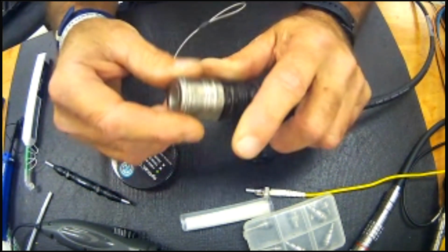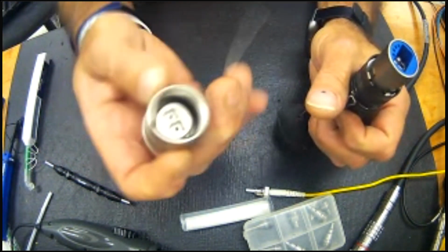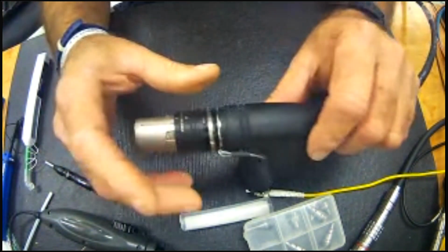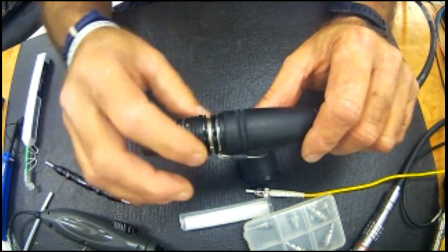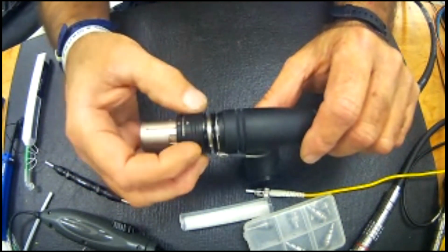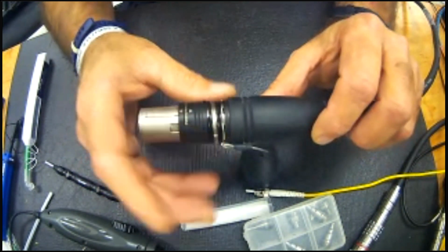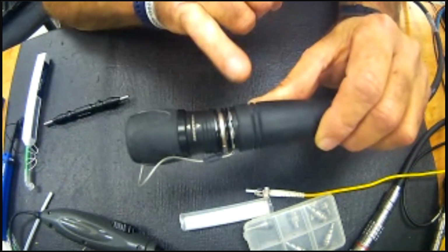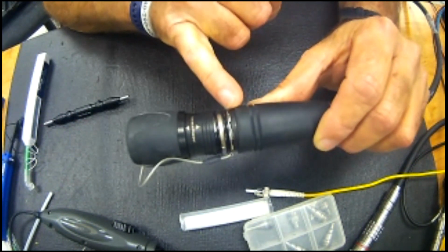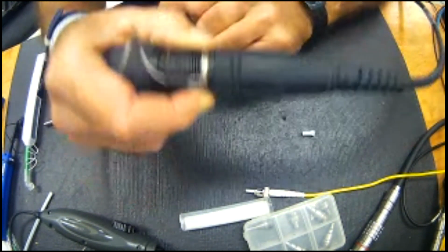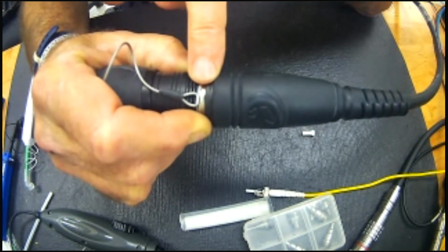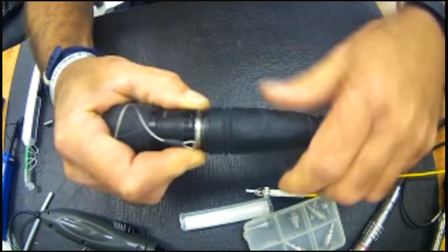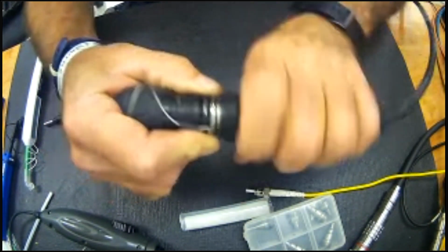That's one approach. Another approach, if you don't own this, because this is proprietary to this connector, is learn to take this connector apart. I've had repairs come to me with channel lock marks and vice grip marks because somebody didn't know that in order to take this connector apart, you have to retract this spring to move this wavy washer, the slotted washer, away from the back nut. Why? Because the back nut has raised teeth on it. So those teeth will stop you from unthreading this back nut.